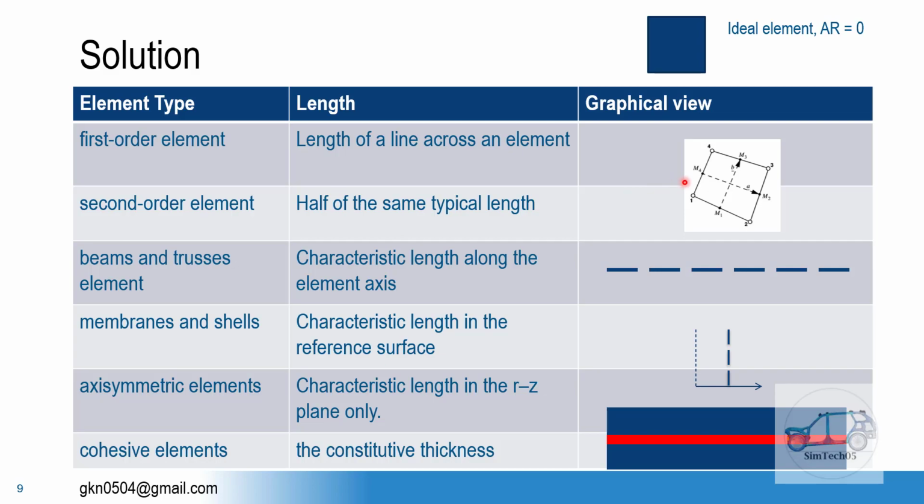That's why in the crack zone, large aspect ratio elements are not recommended, because mesh sensitivity takes place here, and it may be very crucial for crack propagation or element deletion. So try to define very good elements within the crack zone, with an aspect ratio near about 1.